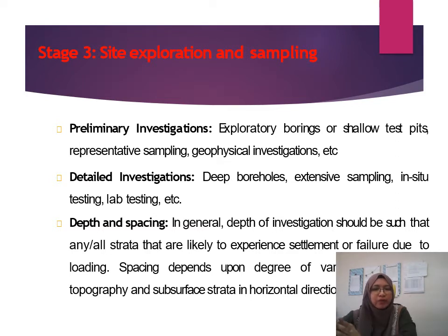So you have to conduct a very detailed site investigation. The depth and the spacing of site investigation should be more. The number of boreholes should be more, and the depth should be very far, until the very hard layer of soil, and the spacing between the boreholes should be less.